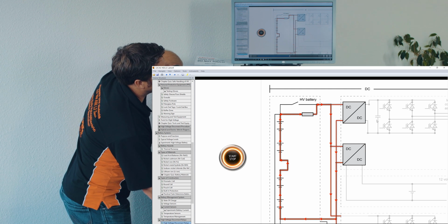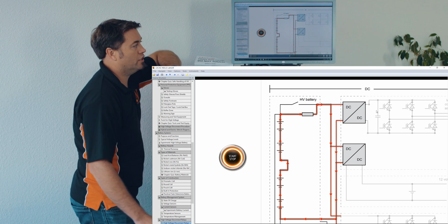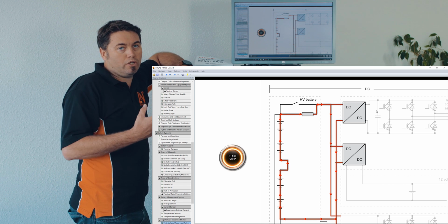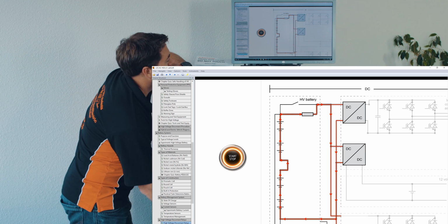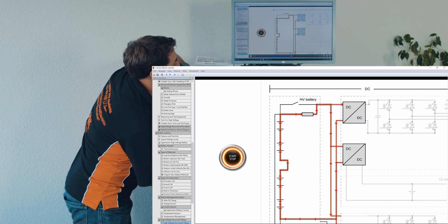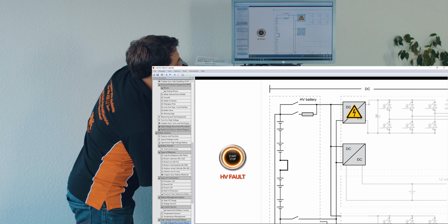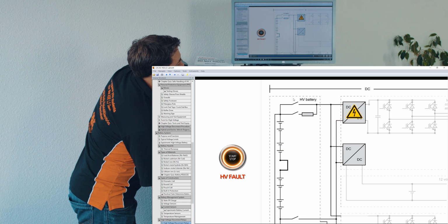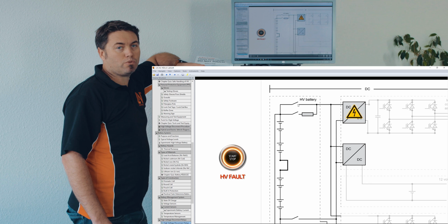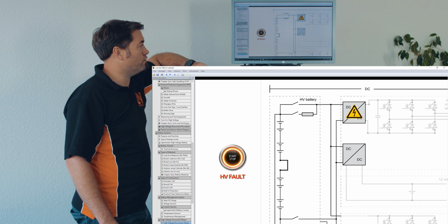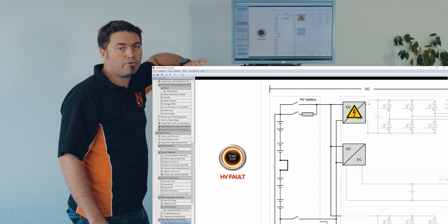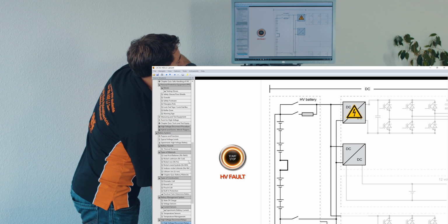It also allows the capacitors inside the inverter to slowly build up, because they can really suck in a lot of power all at once. So if the system realizes there's a fault, it won't shut on the second relay. It'll allow the first one to open. It'll shut down the system after recognizing a fault. It can recognize that also through the current sensors.